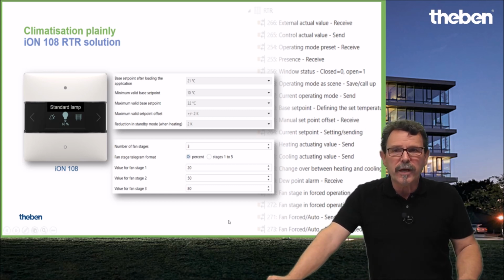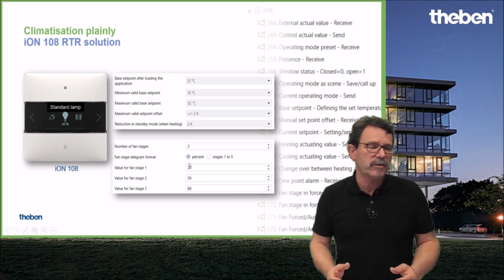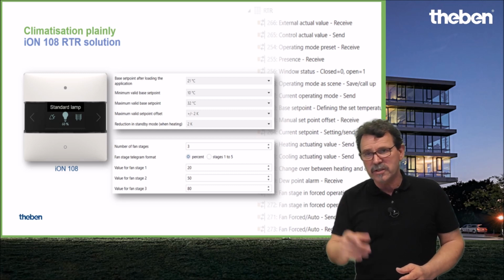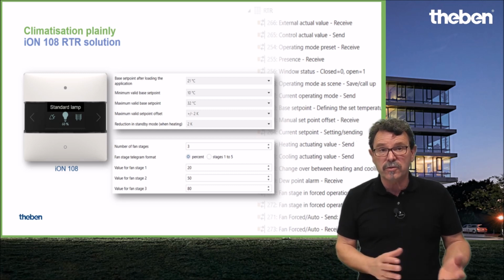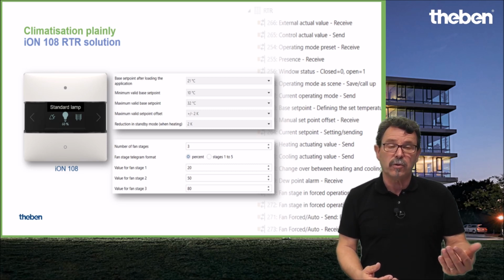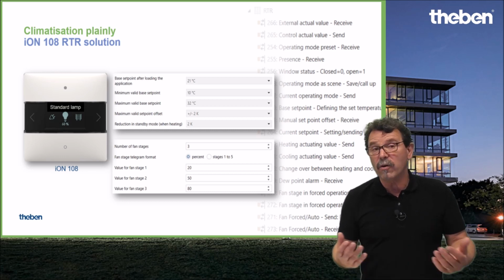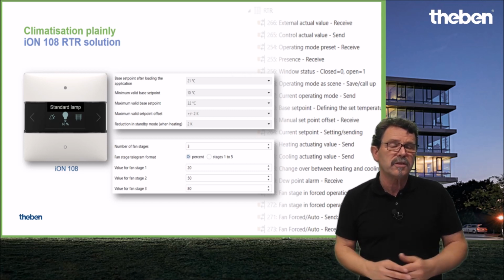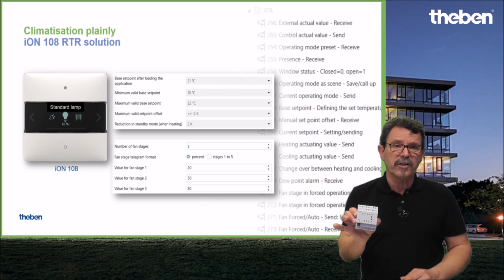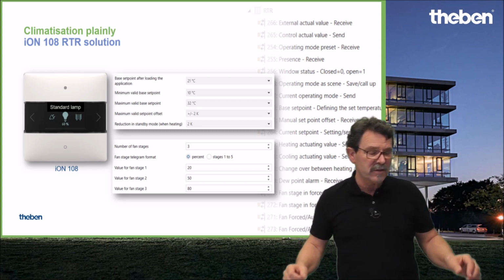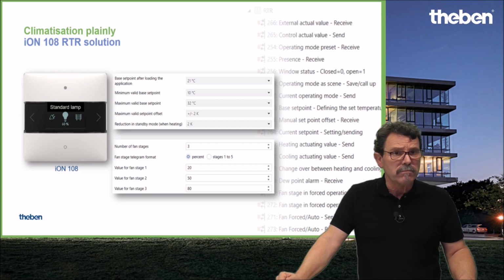Yeah, and when it comes to these fan coil actuators, to support a fan coil actuator, we have to distinguish two different control commands. Either you discover a percentage value, so that means we have 0 to 10 volt control, so a valve can open according to 0 to 10 volt control commands. Or for instance, a fan speed can be controlled with a control command of 0 to 10 volts. Yeah, for instance, this fan coil actuator FCA2 from Theben. So the output here is 0 to 10 volt, or depending on the setting, it can be in stages as well. So what is the difference?